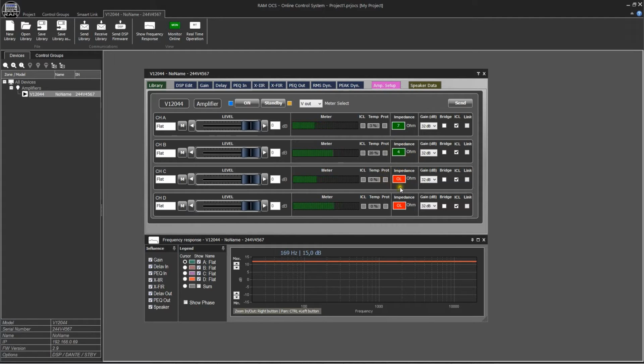When the impedance level measured is not within these user-defined limits, the background will change to red. The OL expression means open load, and indicates you'll have not any speaker connected. If the background remains white, it indicates that there is not enough output voltage to make the measurement. Lastly, we have the option of changing the gain value of the amplifier section itself, as well as the bridge configuration, or to disable the anti-clip system.